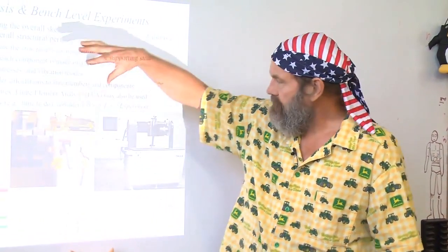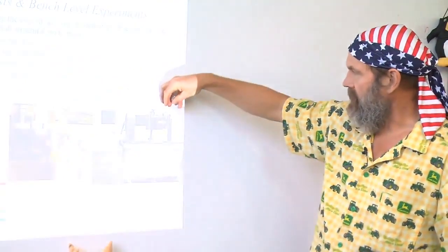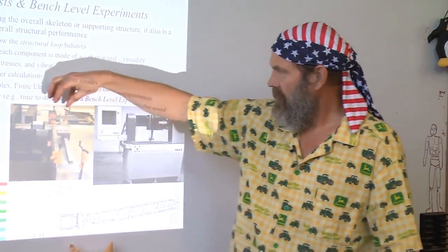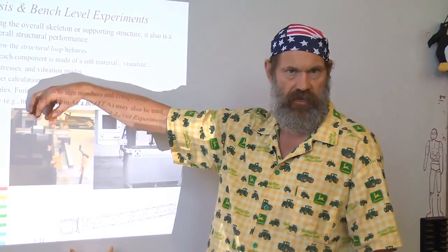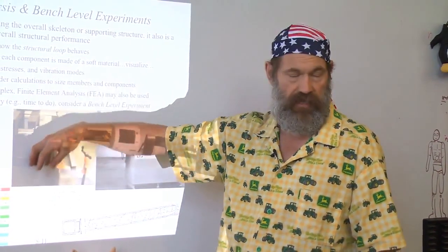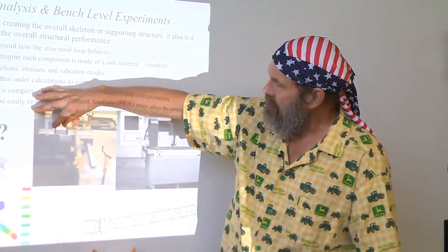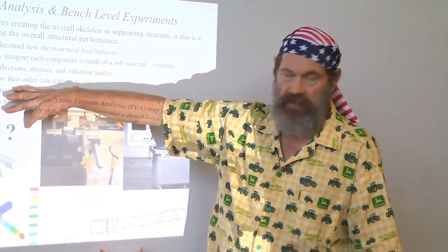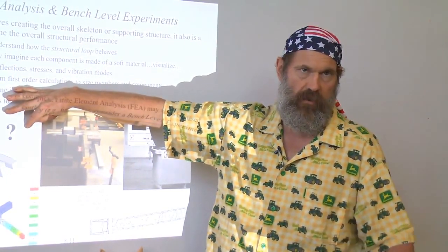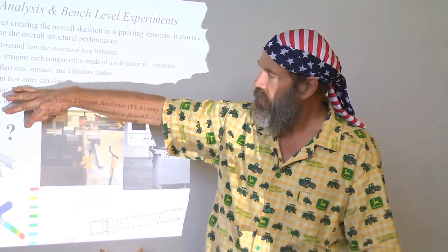Things actually worked out fine and actually very nicely for the small machine size we're looking at. As we went up in size, things didn't work so well. Why? Because remember we talked about earlier, the stiffness is a function of the length cubed. And then one of the functional requirements is to hold the container of sand on the structure. That's the abrasive that's used in the water jet. And as this started to get a little bit longer, marketing said, well, we think we want this, quote, small machine to have a slightly bigger cousin.